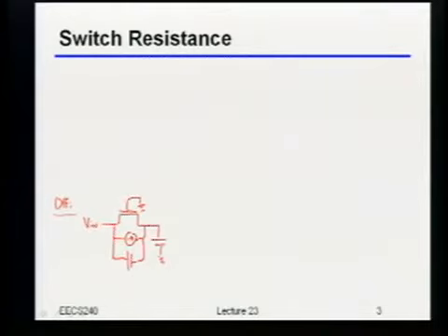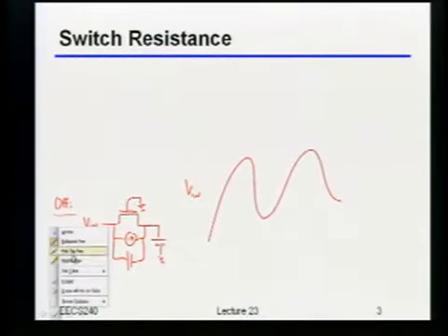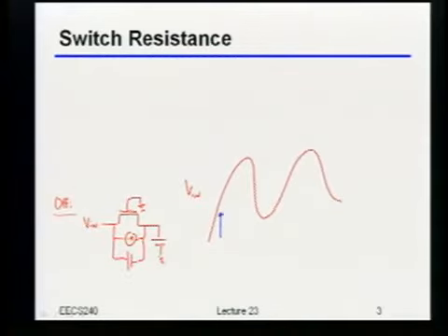Because you can imagine, let me draw V in with some red waveform here. Let's say that that thing is doing something like this, okay? And let's say that I wanted to sample V in just right there. So if I looked at V out, it would track, and then in theory it should stop and just track perfectly like this, right? It should just sample it perfectly like that. Well, unfortunately, what's actually going to happen is that because of that stray capacitance, you're still going to move around along with the input, right? Now, I've obviously exaggerated it quite a bit here because I'm tracking almost perfectly with the input. But basically, just that capacitive divider means that I'm going to feed directly through, right? So my output's still going to wiggle around even though I've tried to turn the switch off, okay?